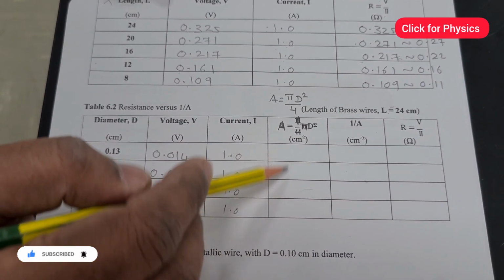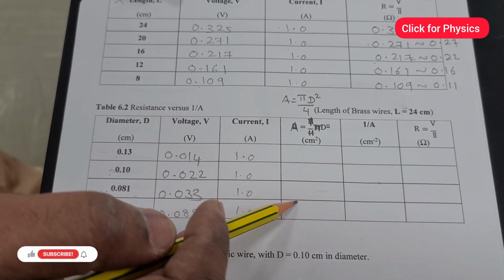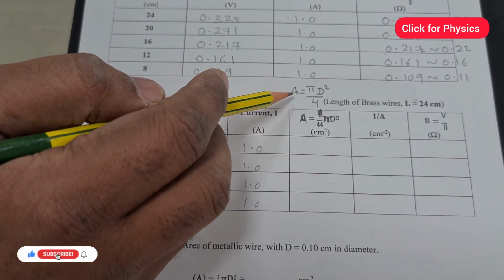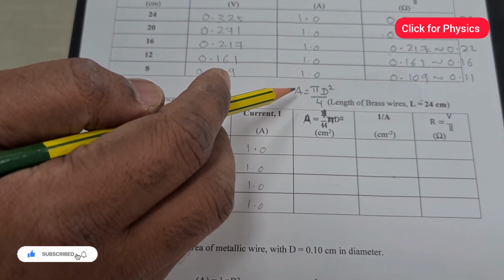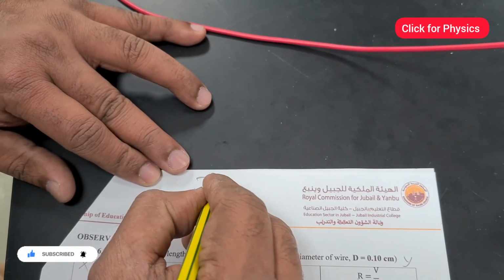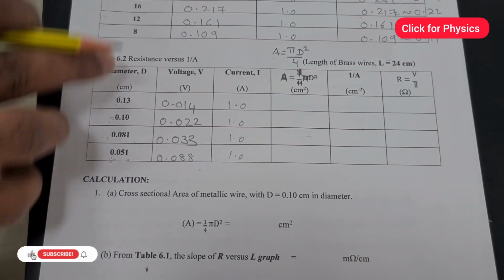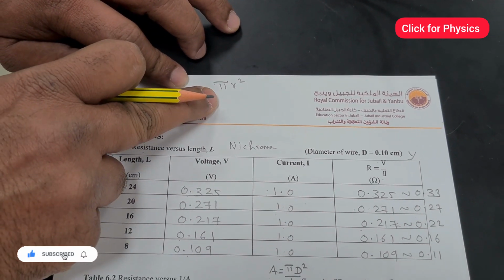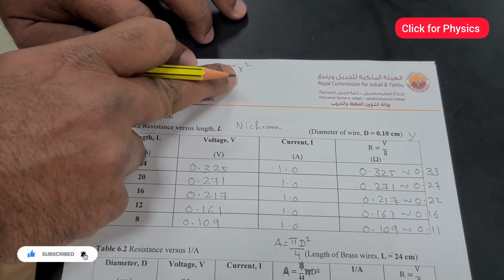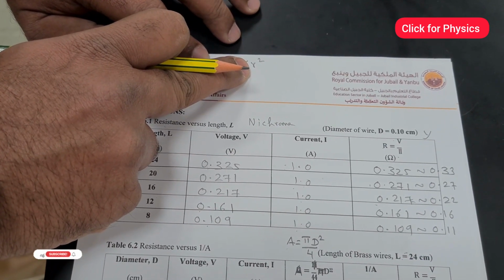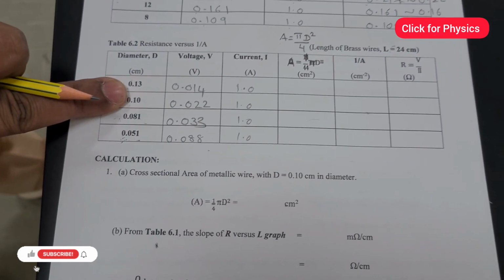So here we are going to find its respective area for each diameter and the formula is given here. So what's the formula? The cross section of the wire looks like the area of the circle. As we know, the area of the circle formula is pi r square, right? But here we are using the diameter. So I am going to modify this formula in terms of diameter, because here we have pi multiplied by radius square. So I'm going to convert this radius in terms of diameter. Why? Because in the table we are going to use the diameter value.